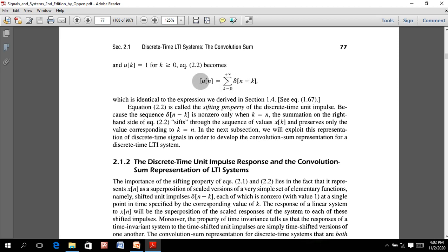So a step response can be defined with the impulse response, and the specific signal can also be realized using impulse signals. That is the most important characteristic that we are going to discuss in the next lecture. Up to this we have realized what an LTI causal system is, and why we can express any kind of discrete time signal using impulse signals. A specific discrete time signal can be realized as the summation of different impulse signals.